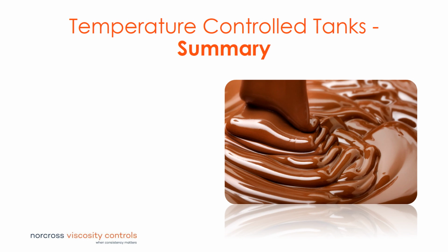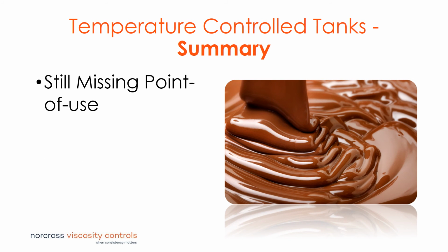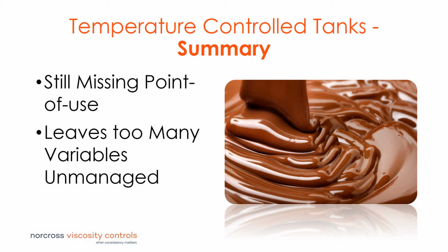And so to summarize, temperature-controlled tanks still miss controlling at the point of use. When used alone, temperature-controlled tanks leave too many variables unmanaged. Like temperature-controlled rooms, once the fluid leaves the tank, the temperature control ends. Without additional hardware, these can still leave temperature variable at the point of application. But that is not to say that these are without value.